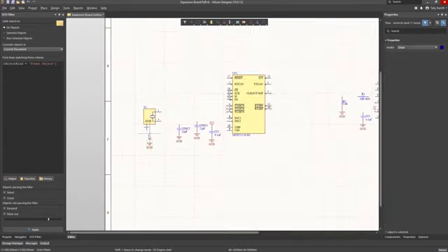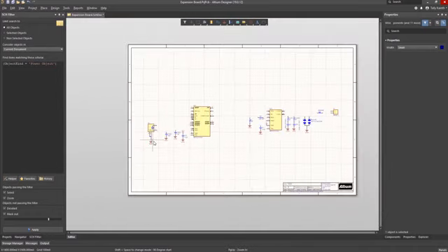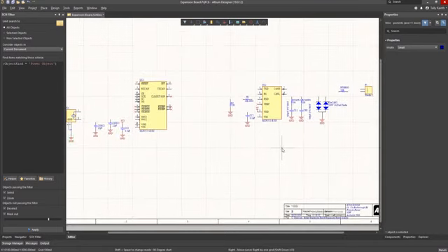Placing wires manually is done using the active bar menu Wire option. Right-click and select Place Wire. Now we are in the Adding Wires mode. Left mouse click on the start of the wire and then move the mouse to place the next wire vertices and left click again. A single click ends the wire but keeps you in wire mode for placing additional wires. Also, whilst placing a wire, hitting the spacebar will flip the vertices of the active wire segments if required.